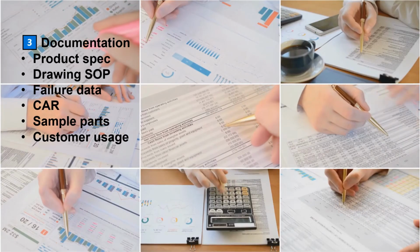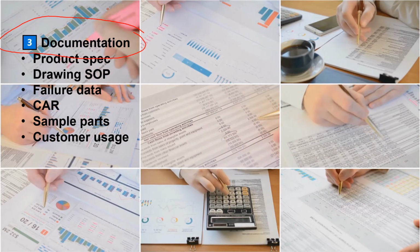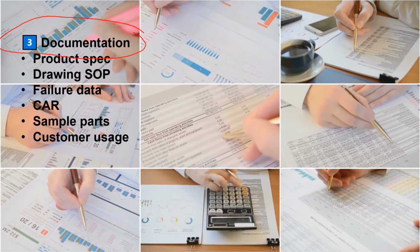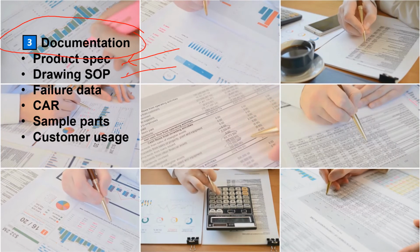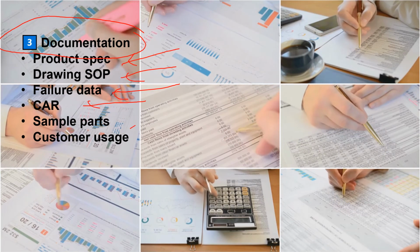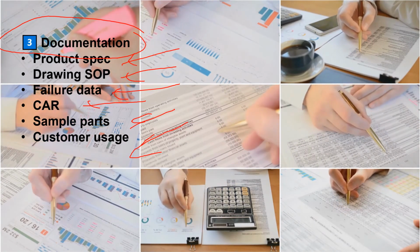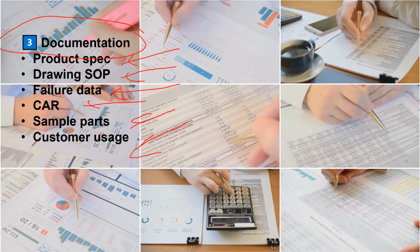The third item in the list would be documentation. Ensure that the FMEA team compiles all the necessary documentation to understand the current situation, and these will include the product specs, the drawings, SOPs, the failure data, the corrective action reports, sample parts, customers' usage environment, etc., to help relate the failure mode to the process or the design of the product.